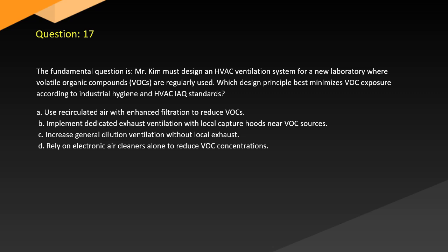A. Use recirculated air with enhanced filtration to reduce VOCs. B. Implement dedicated exhaust ventilation with local capture hoods near VOC sources. C. Increase general dilution ventilation without local exhaust. D. Rely on electronic air cleaners alone to reduce VOC concentrations.